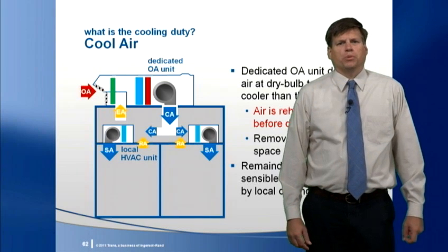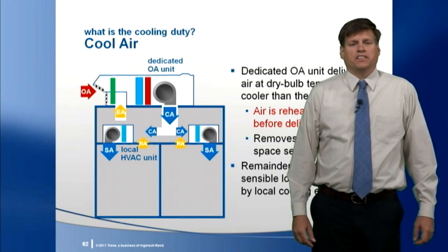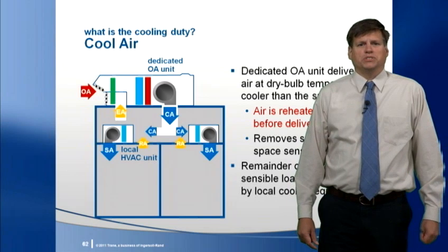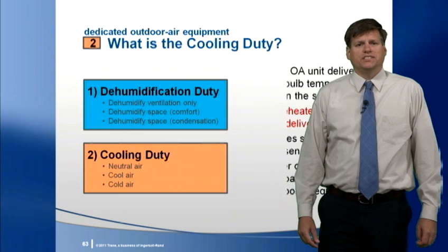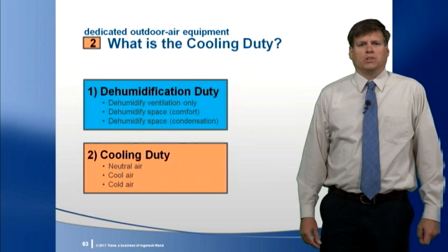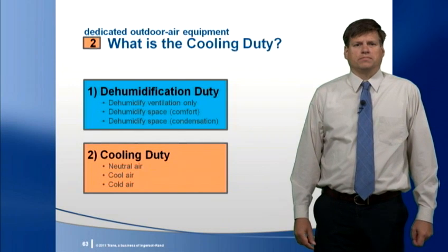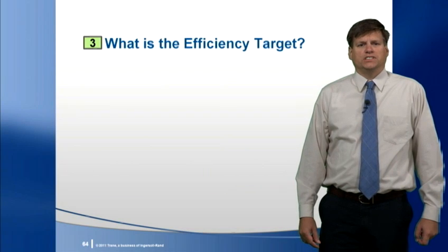Or in applications where the required dew point is very low, the design engineer may want to reheat the air up some before delivering it directly into occupied spaces. This defines the second piece of the puzzle. What is the cooling duty? The third goal is the efficiency target.